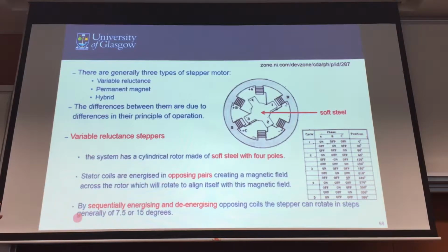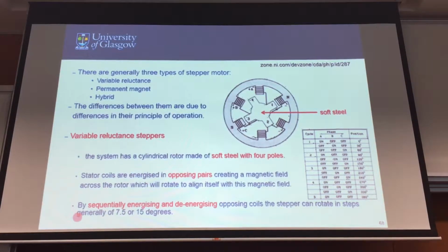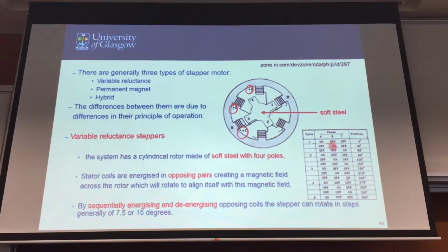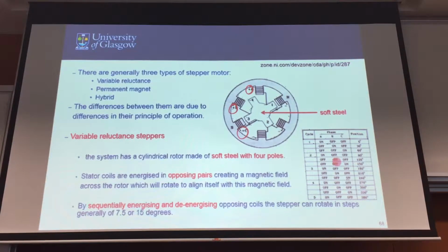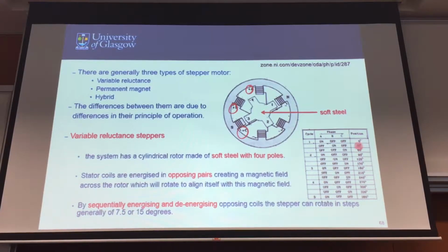This is one construction of the stepper motor where it uses that rotor as the core, and the material is soft iron. So you could see that for this A coil, B coil, and C coil, there's a certain on-off format that you can put in, and that is what we call the digitization signal that you can supply, either on or off to those 3 coils, and correspondingly you get its position.